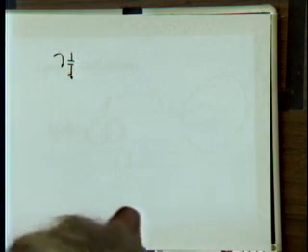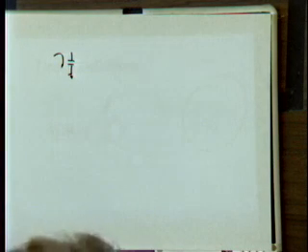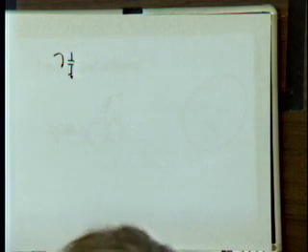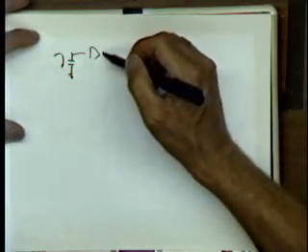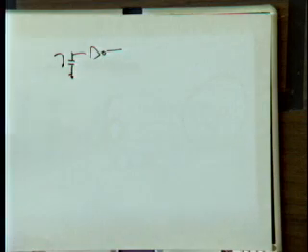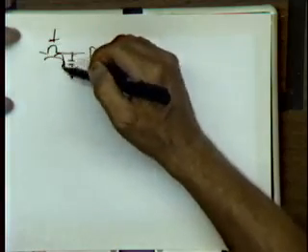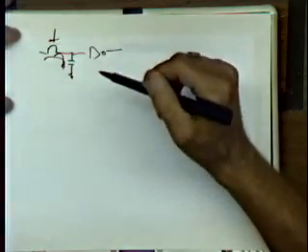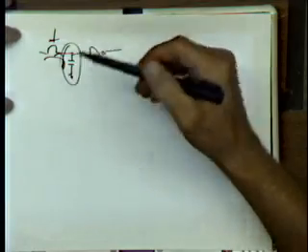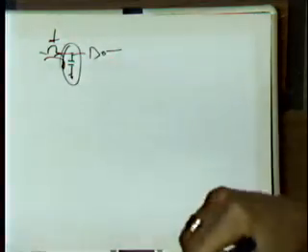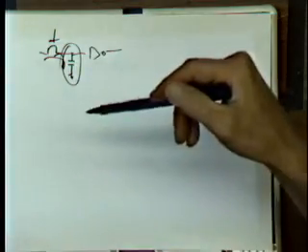So capacitors are perfect memory elements and quite cheap, because whether you want it or not, we have capacitors everywhere in a logic design. One way of storing things is just putting charge in the capacitor and later measuring what you have on it, for instance using an inverter. Obviously this has some problems, because anytime I connect something like a transistor here to put the charge on, we will have leakage. So the charge is only going to be there for a certain amount of time, and then you lose the value.